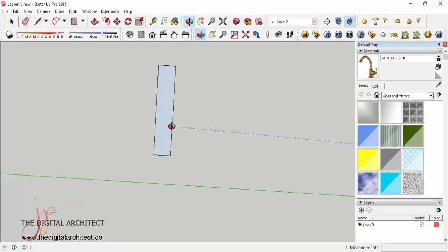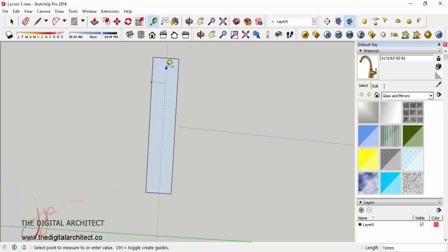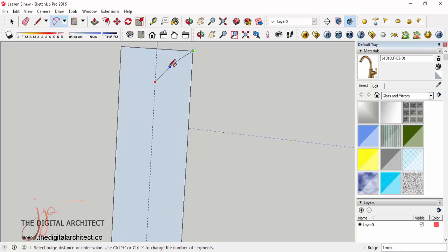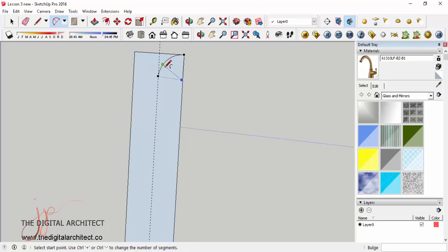And we will do some molding. Just imagine you're cutting the skirting in half, so what you will see there. Let's just make it up. Maybe it will have a round face here, so I will use the arc tool and then select anywhere. It doesn't have to be exact, then create an arc there, and that will go down maybe 40.